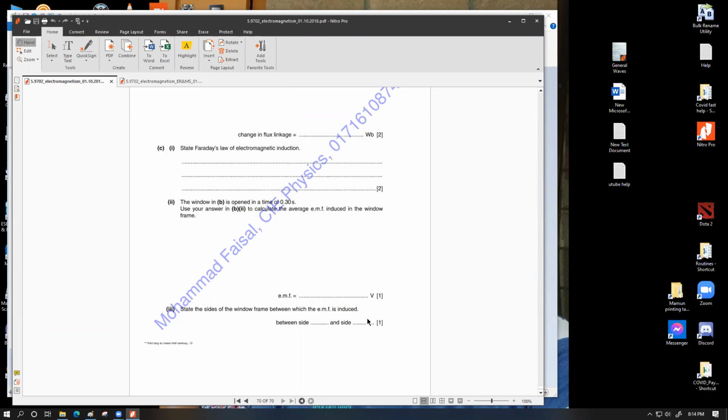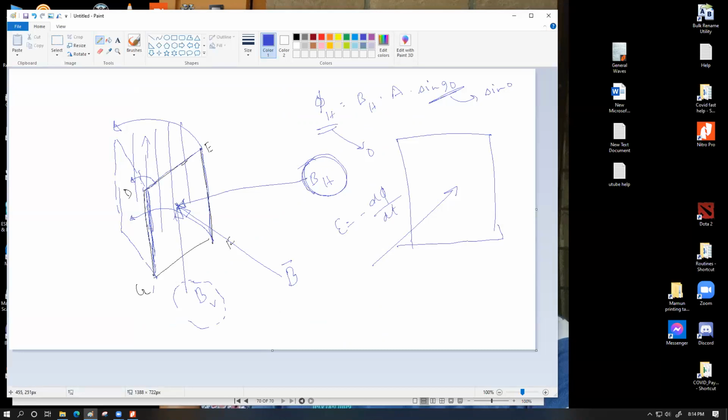Whatever you write will be correct, because all the individual phases would give you some voltage difference, except exclusively if you connect a voltmeter across D and GF, because D would be cutting across the vertical component of the field lines at the same rate as GF. So at any instant of time, the voltage produced by either of them would be exactly equal. Numerically, that voltage would be equal. So if you try to get a voltage difference across them, you're not going to get a voltage difference.